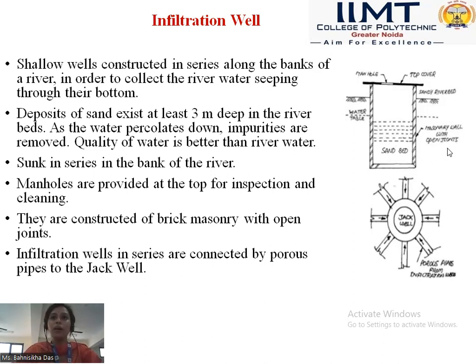The water will keep entering till the head becomes equal, and then all these wells are connected to a particular jack well from where the water is taken to the treatment plant. However, since this is underground water, the treatment cost is very less in such cases.